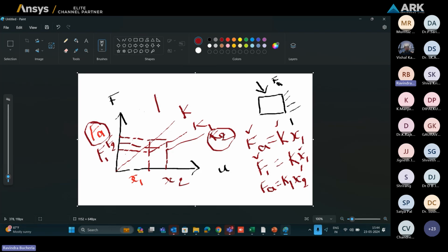So ideally, this is the ideal case, the force applied and the force reaction that we are getting are equal. Then we will consider the solution as converged. Whenever the force applied and force reaction are equal, whatever the displacement that we get, that might be x4 or x5, that displacement will be the correct displacement.